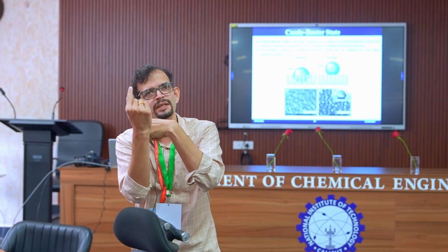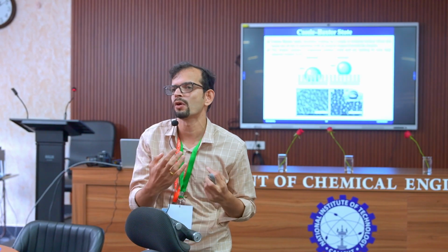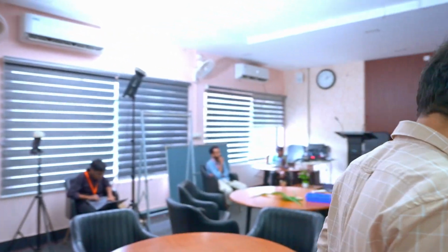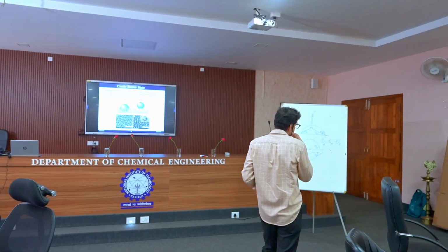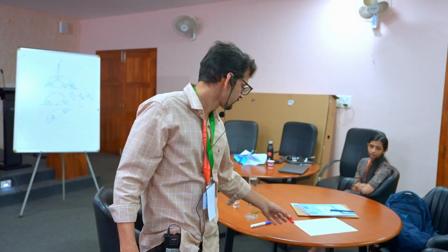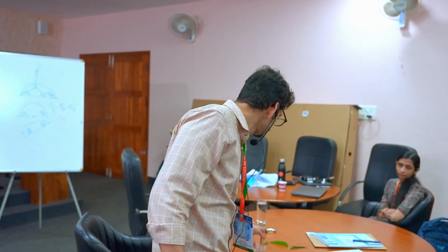Along with that, the contact area is significantly reduced. We already understood that chemical and physical interaction effectively leads to hysteresis. Here the hysteresis will be very, very low, because the contact area it forms is very small. Such states are called the Cassie-Baxter state. The previous case is the Wenzel state. The classical example for Wenzel is our rose petal, and for Cassie-Baxter it is our lotus leaf. I hope things are clear up to now.